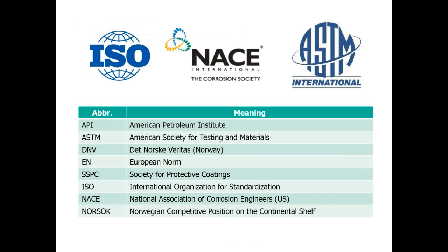There are many more. In the interest of time, I'll go to the inspection, but essentially there are standards out there that outline the procedure for preparing, testing, and corrosion reporting. So for example, NACE has many standards, but keep in mind that ASTM has a lot of standards for testing metals, as well as ISO. SSPC is big on corrosion coatings, as well as NACE. Even the API has particular standards.